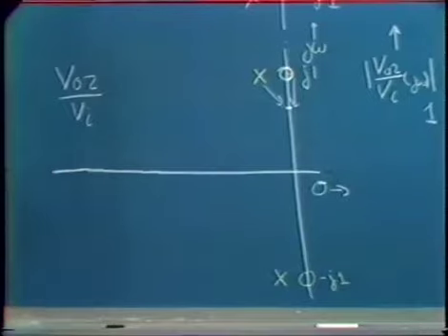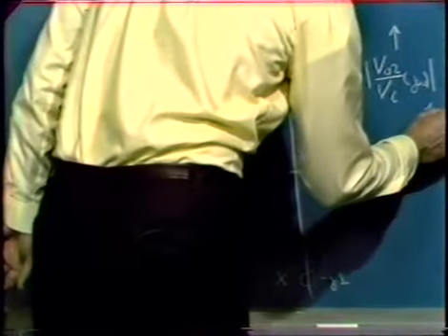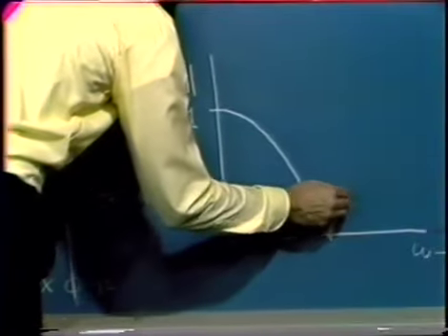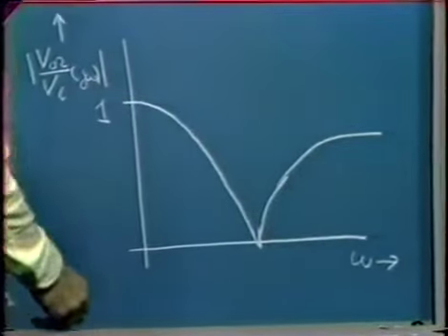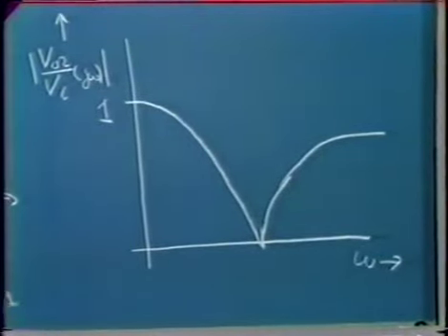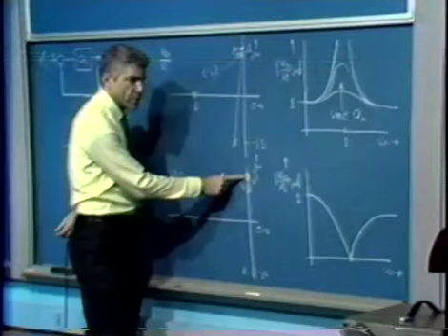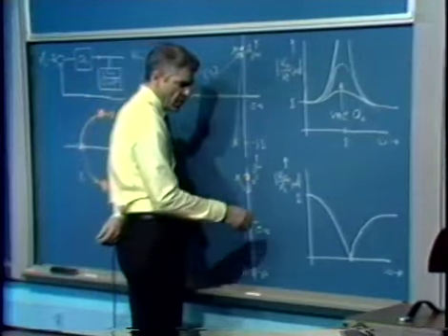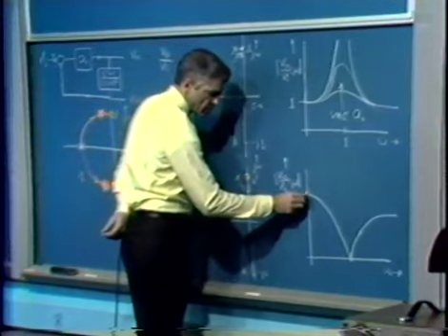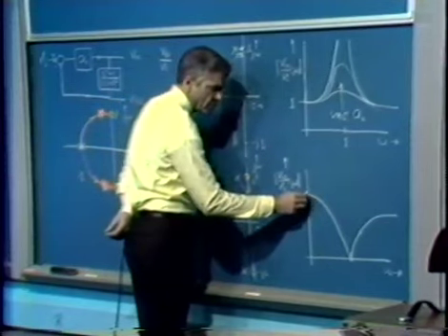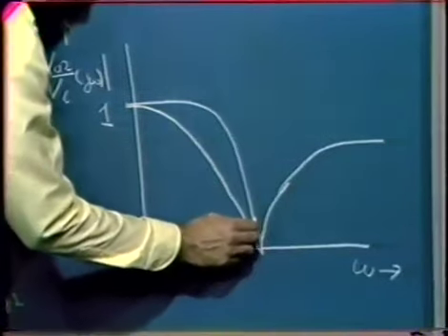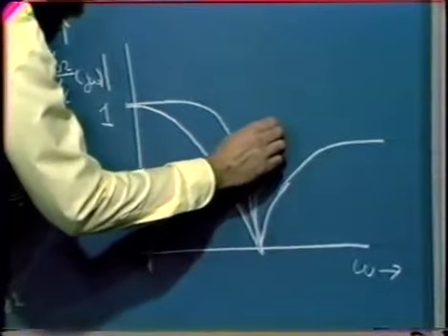So here we'd anticipate a rejection amplifier where the response really goes to 0 at 1 radian per second. And now, as we increase A0 and bring this pole closer to the 0, the range of frequencies over which the cancellation does not occur between the vector lengths gets narrower and narrower, and we get a much sharper null.